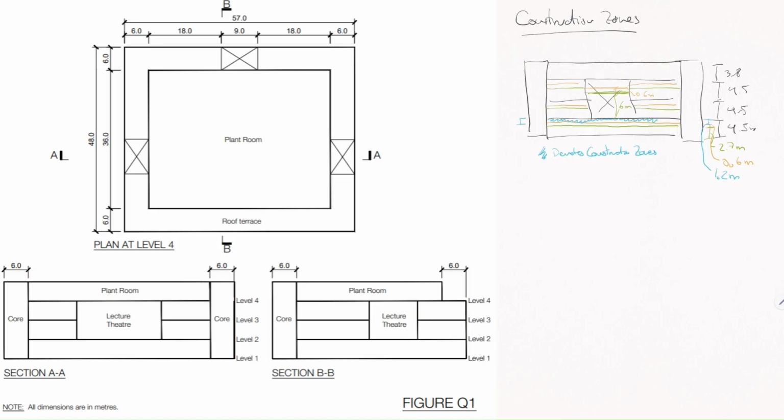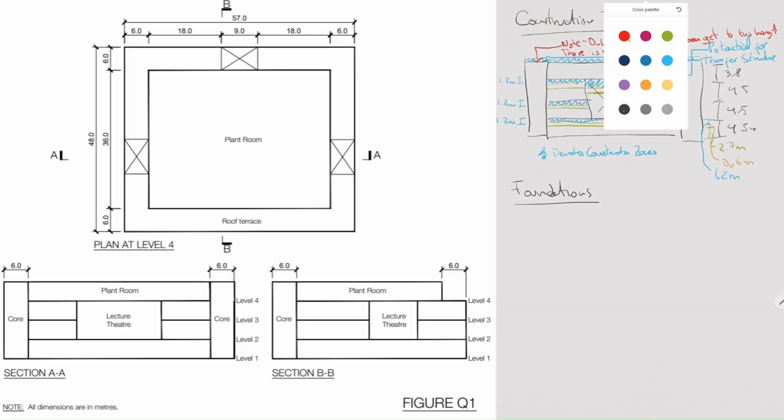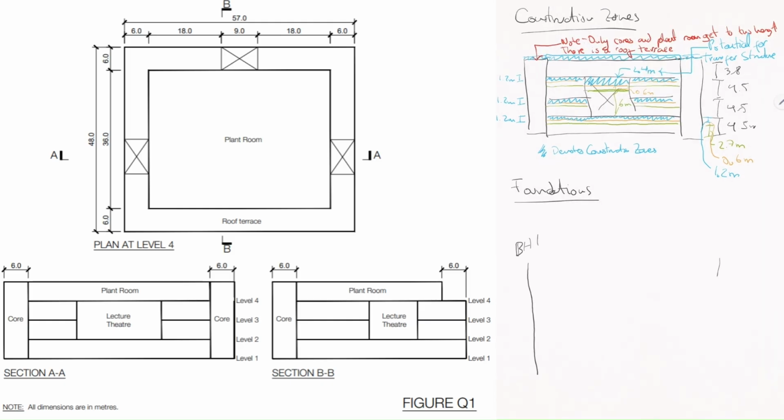So I'll draw an elevation or a section, cross-section, and then follow the client requirements on what's the ceiling height required, if there's any M&E depth required, and then the remaining between the expected floor level and the floor level above. Then that's the area that is called construction zones, where I can put my structure, my beams, and my floor.